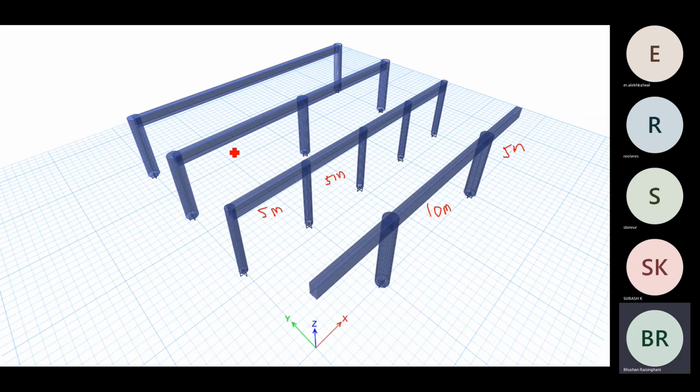Okay, this is again 10 meter and this is 20 meter. So these types of frames you should test without application of any load. This is only the dead load condition. So in the dead load condition, what is the effect of the vertical earthquake that you should consider? And then you should try to realize what the effect of vertical earthquake is. If there is a large overhang or a large span, then what type of oscillation or what type of time period is there in the structure?